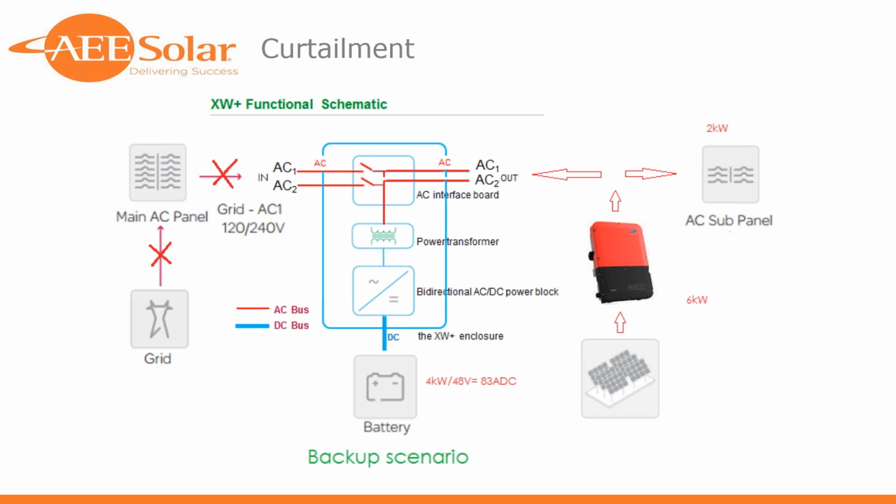This being a student project, they didn't have a ton of money and they didn't really have anywhere else in the house to put more battery. What they did is they took one of the PV inverters offline and they kind of downgraded the system to a 5 kW system. So this is not an unheard of event when AC coupling, where your PV inverter didn't necessarily line up with the wattage of the battery inverter.